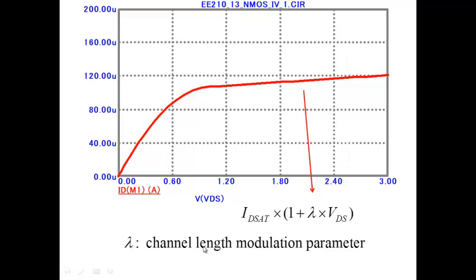The excess voltage here is what controls the current. So there's a parameter called the channel length modulation parameter, which says that the channel length is reducing with voltage and the current is increasing as a result of that. This is the parameter lambda which models that phenomenon, by saying that the current actually increases a little bit here. It is the counterpart of what we were talking about, early voltage. Early voltage in the bipolar transistor was as you apply larger and larger collector emitter voltage. Remember we had e to the power QVB by KT times 1 plus VCE by VA. And the counterpart of VA is 1 by lambda. Lambda has units of 1 over voltage. And so this is the counterpart of the early effect in MOS here.